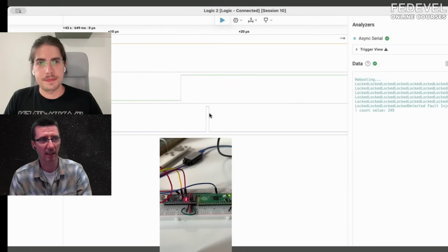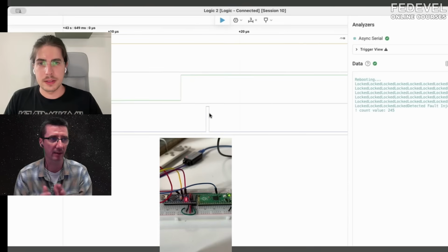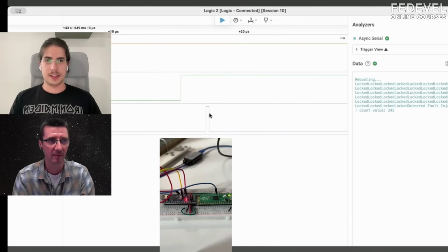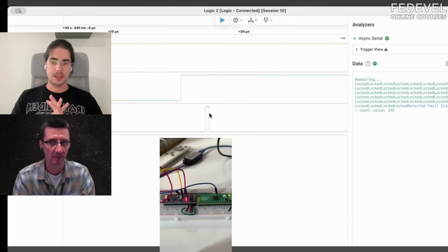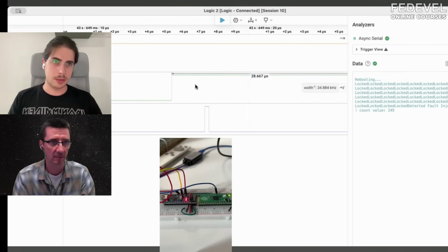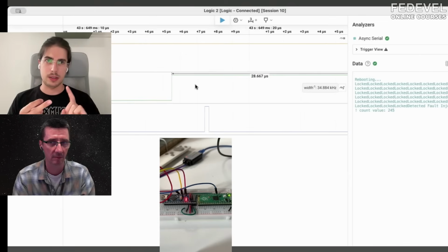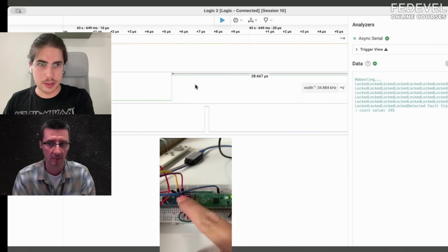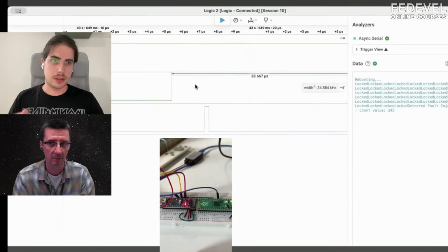So right now these pulses are completely random width and random place. Yeah, it's just to make it simple. I randomized the width and the delay and everything. And in reality, if I wanted to hit a certain instruction, I would estimate it from the disassembly, from knowing the clock speed of the device, and from roughly estimating where it should be, and then I would sweep a certain range earlier, later, because of course we have physical effects. We have different clocks on the Pico and on this. They are not synchronized. So these are different factors to think about.